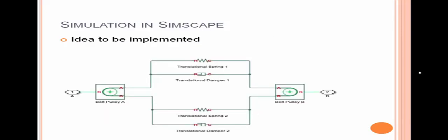So to model the belt conveyor, there are several components that must be present in our simulation. The head and tail pulleys, here you see them at the two sides of the belt conveyor. The pretension weight as well as the belt material itself have to be modeled.